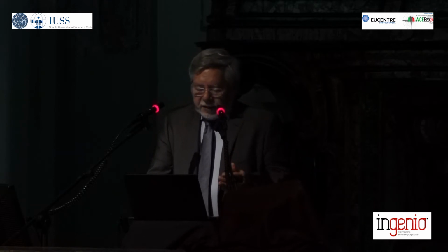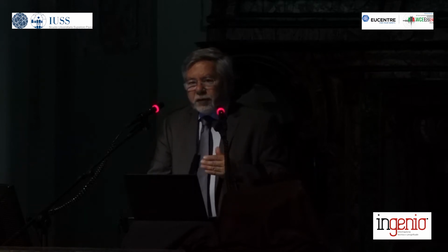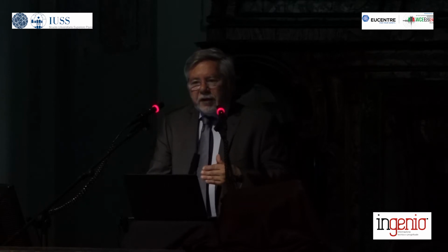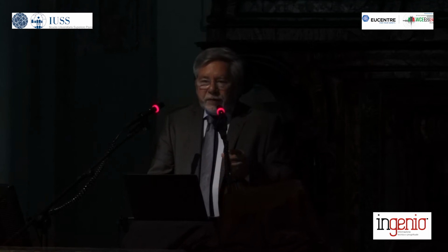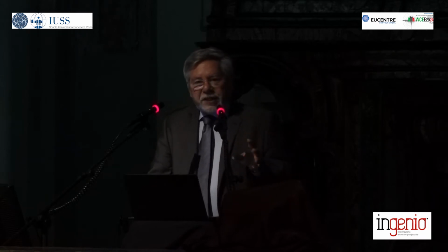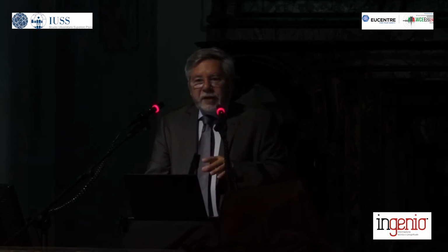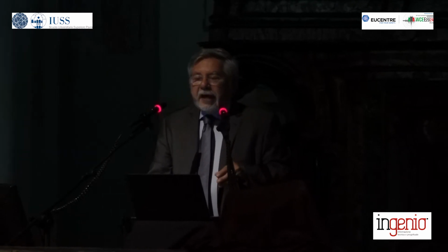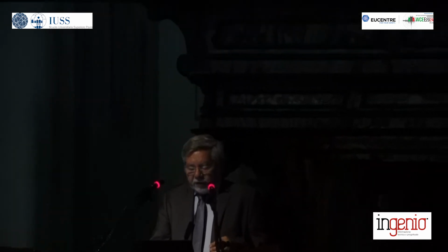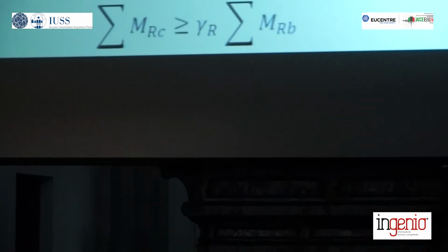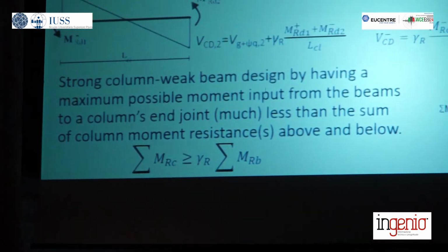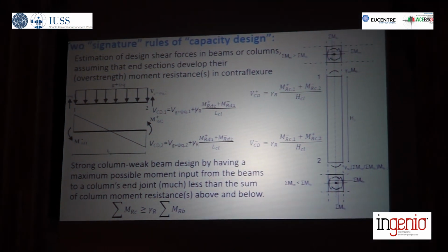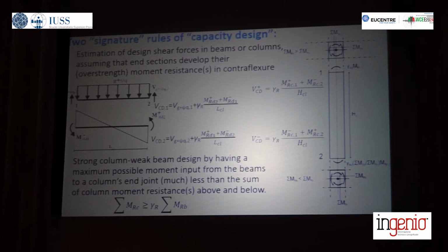One is the derivation of shear forces in concrete beams from the moment resistances at the two ends using just equilibrium and assuming that the beam is in contraflexure. The same for columns.